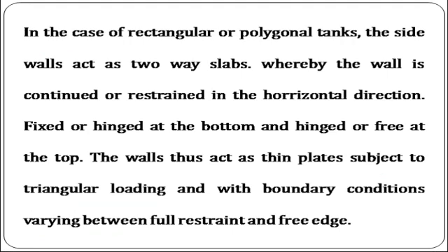So in the case of a rectangular or polygonal tank, the side walls act as a two-way slab, whereby the walls are continued or restrained in the horizontal direction.